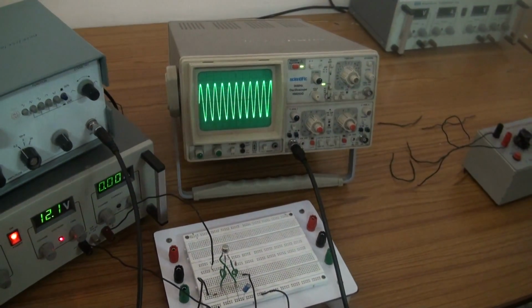Now we can conclude that this amplifier is amplifying the input signal, right? Yes. So this is what you have to test in the circuit first. First you have to test the circuit before taking the readings. Make sure that your circuit is working as an amplifier. Then you can vary the frequency, note down the output voltage. We are going to keep the input constant, I told you. Then using formulas you can calculate V0 by Vi. Vi is constant throughout. Only V0 from CRO will be different, so gain is also different.